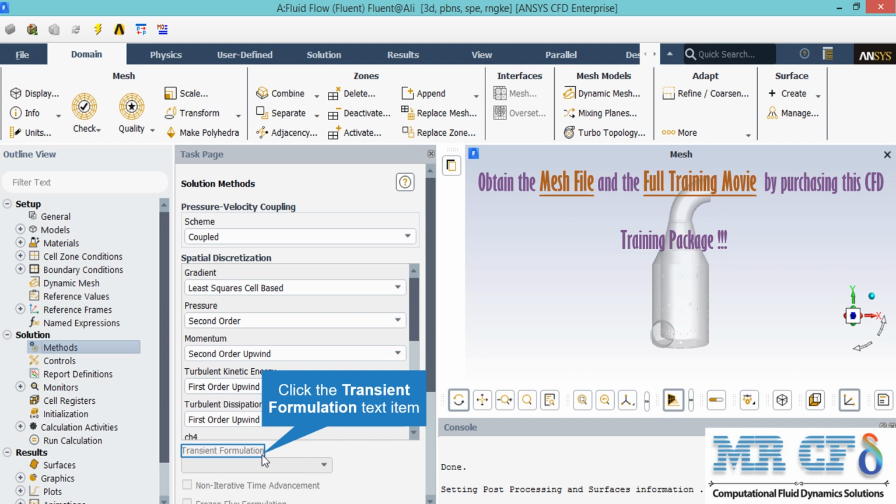Also, you can see that the spatial discretization methods are shown in this window. For example, the pressure discretization is defined to be second order, and for the momentum, second order upwind. Also, you can change this discretization into other formats, like first order upwind.